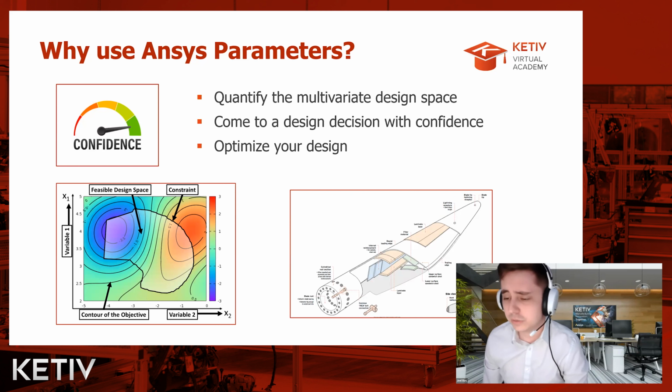I worked in wind turbine blade design for a few years, and one of the things we were always trying to do is quantify this design space. One of the ways we do that is by changing the thickness of the material that constitutes the blade, the fiberglass, right? And seeing how that changes the global stiffness of the blade, like how much it deflects at the tip, for instance, if you were to change the thickness of the main spar beam throughout the length of the blade.